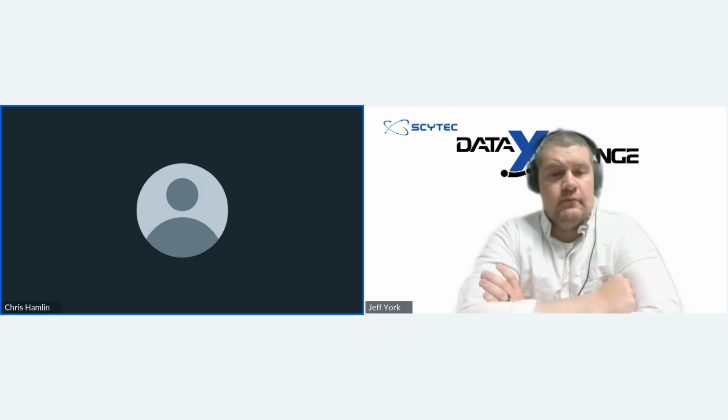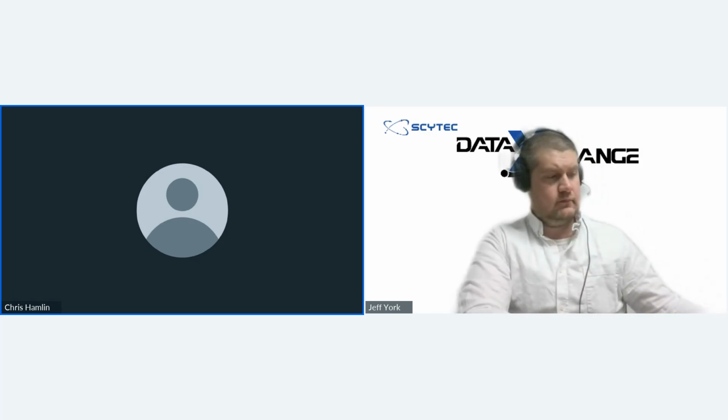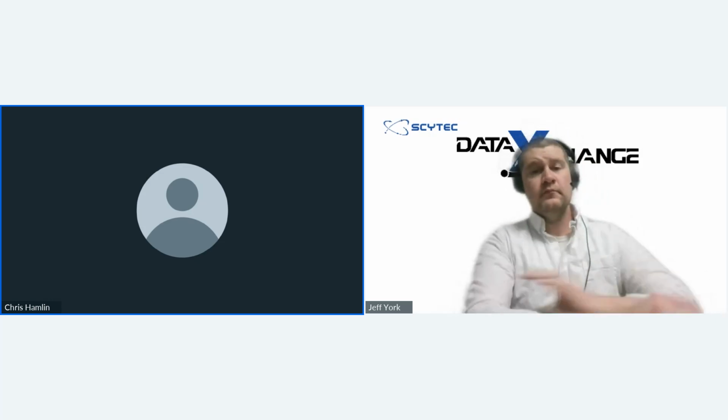You can also set up notifications around that as well. Jeff brought that up a little bit. Notifications can be triggered your way and how you would like to see them. So if you want a notification if the feed rate's been turned down for over an hour, there's obviously something going on with that machine. Maybe there's some chatter, the bearings going out, something of that nature, and you can get an email automatically sent out if that's the case.